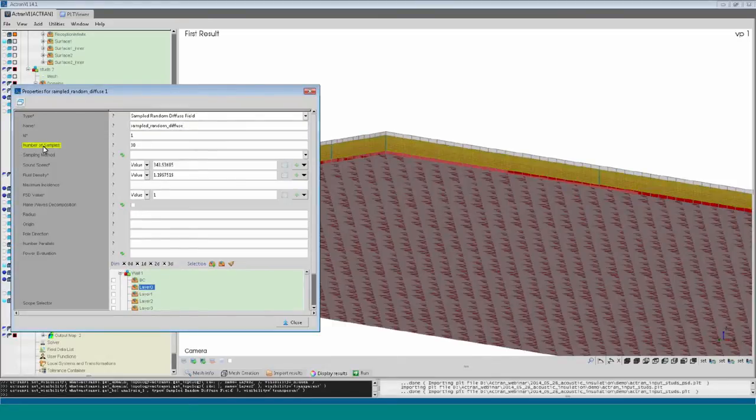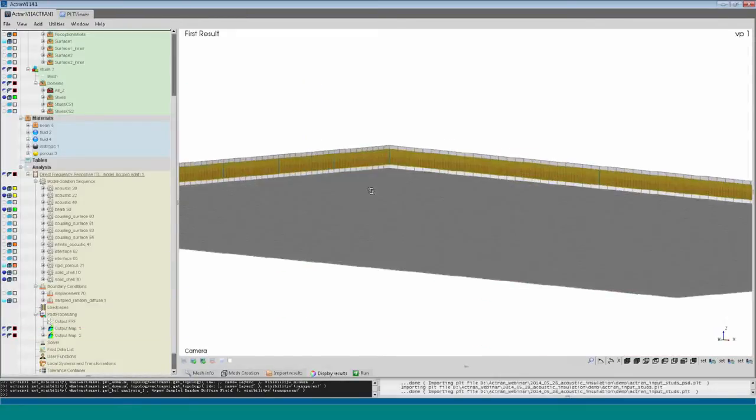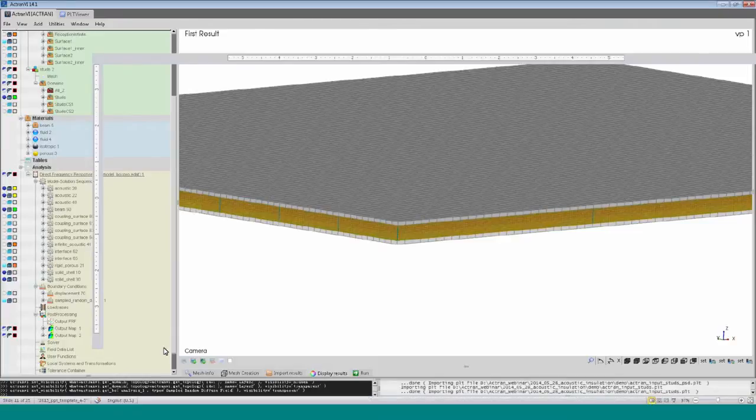And then we specify the number of samples. This is 30 here, and according to our experience, it is sufficient for this type of problem with this type of size. And then we need to define the properties of the medium in touch with the surface, or the medium from which the diffuse sound field comes from. So it is the speed of sound and density of air, simply. So in this way, we define the diffuse sound field. Okay. Now I will come back to the presentation.